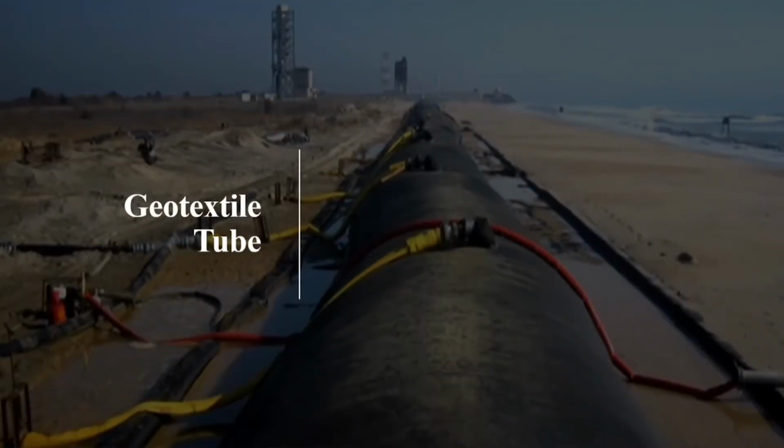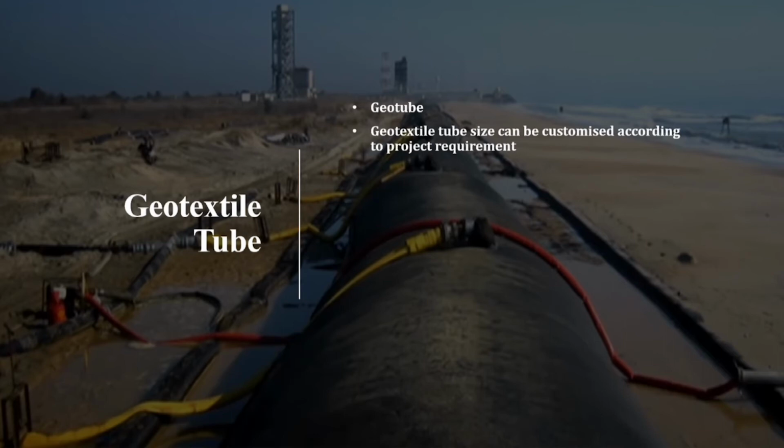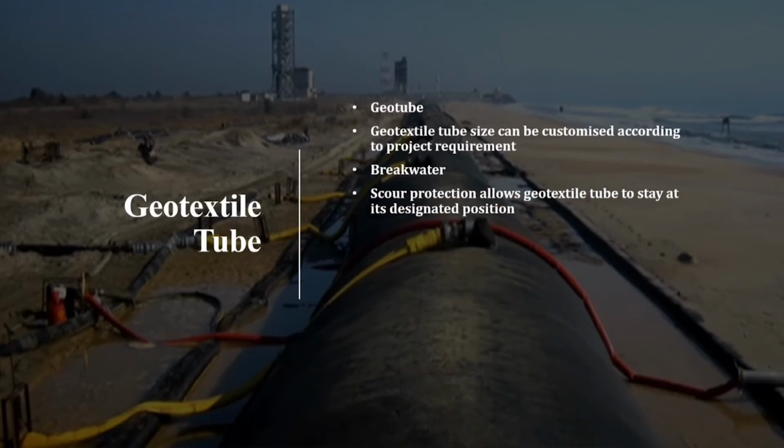Geotextile tube, also known as geotube, is a leading alternative in protecting the shoreline. Unlike conventional materials, geotextile tube size can be customized according to the project requirement, which increases the popularity and worth of the material. Geotube in this particular study can simultaneously serve as a breakwater as well as re-nourishment of the beach ecosystem through the increase in sand deposition after application. Made up of several parts consisting of the core material, armoring layer, filtering layer, and scour protection, it allows water to flow through the pores while retaining the infill sand without causing the geotube to move from its designated position, acting as a breakwater to prevent further erosion of the shoreline.